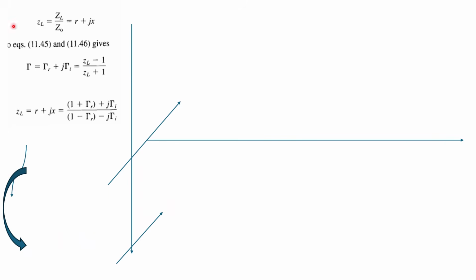So now, since transmission lines may have different loads, we are going to construct the Smith chart which will be valid for all types of transmission line, irrespective of their values of impedance load. So how is it possible to construct it for all? That is why we are going to normalize the load. How do we normalize? Just divide your load by Z naught.